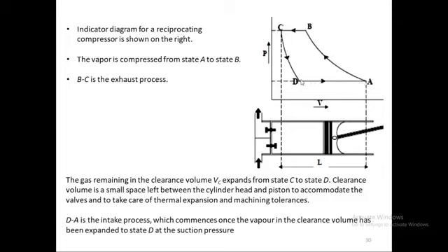So the actual volume of the gas which is being compressed and the volume of the fresh gas which has been taken in are different. It is not the same as the swept volume, because the swept volume must include some portion which was the trapped gas that expanded. So that's the difference between the swept volume and the actual compressed volume.